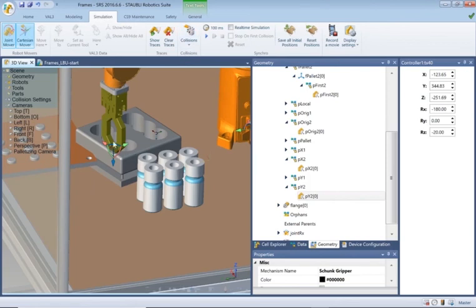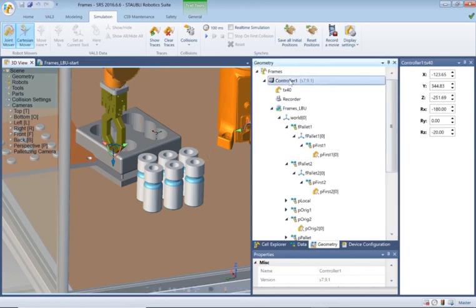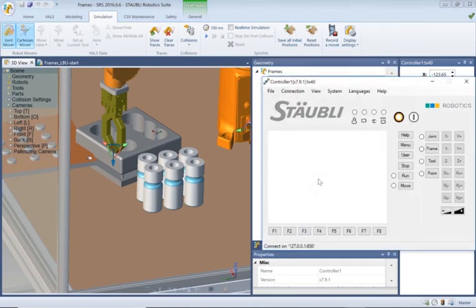Go to the simulation. Now we've moved the palette. What we need to do is remember to save the initial positions again. Let's save it. Everything's good. So when it palletizes and we want the bottle to come back out, if we didn't save the initial positions, the pallet is considered as a part and it would jump back to its original position. We don't really want to do that. Let's go to the top and run the emulator. I don't have to simulate it because it's going to take that code and just do the calculation again.